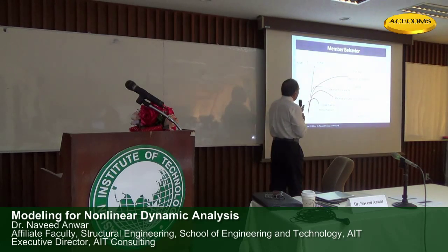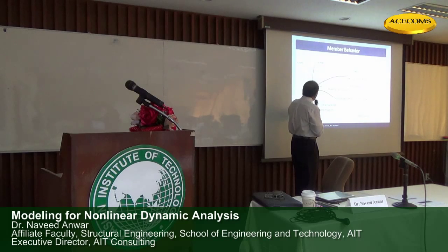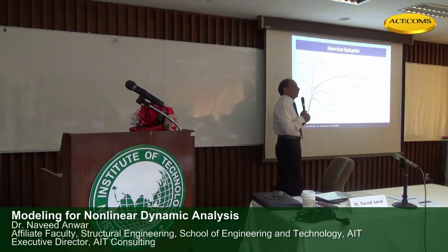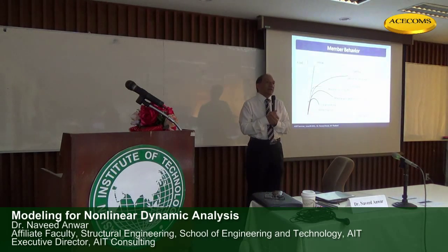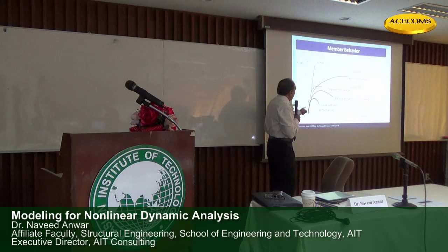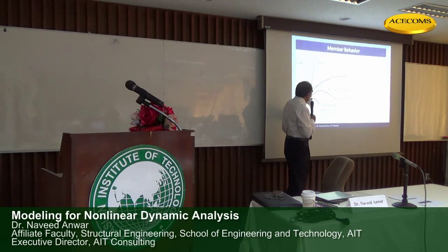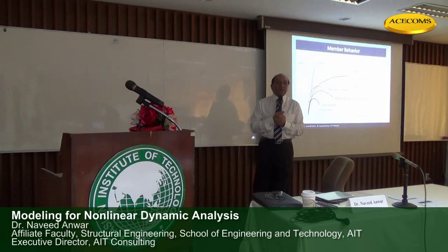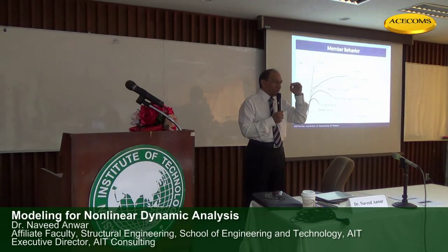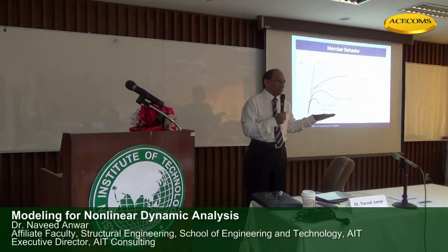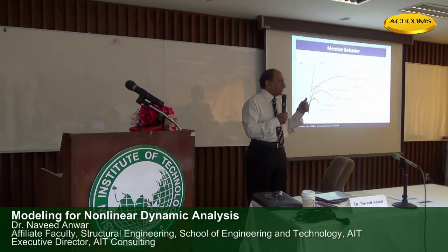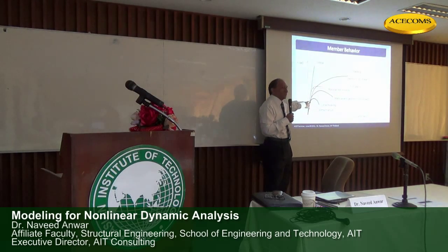But actual structures, actual members start to deviate from this line at some point and then go in different ways, depending upon what type of nonlinearity is happening. For a brittle member, it will just stop and cross here. It will not become nonlinear. So a brittle member will collapse when its capacity is reached, break, and finish. There is no nonlinearity. So it has one step, this X mark. So nonlinearity will not start.